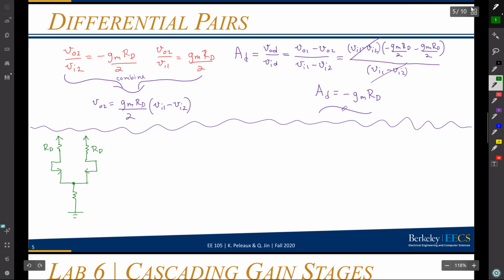And really, we're just assuming that we're going to have some gate voltage, DC voltage generated here. But I'll call that resistance RSS, and I'm looking at the common mode circuit here. So I'm going to think about the inputs being equal. Then I have my two drain currents, ID1 and ID2. This is M1 and M2.